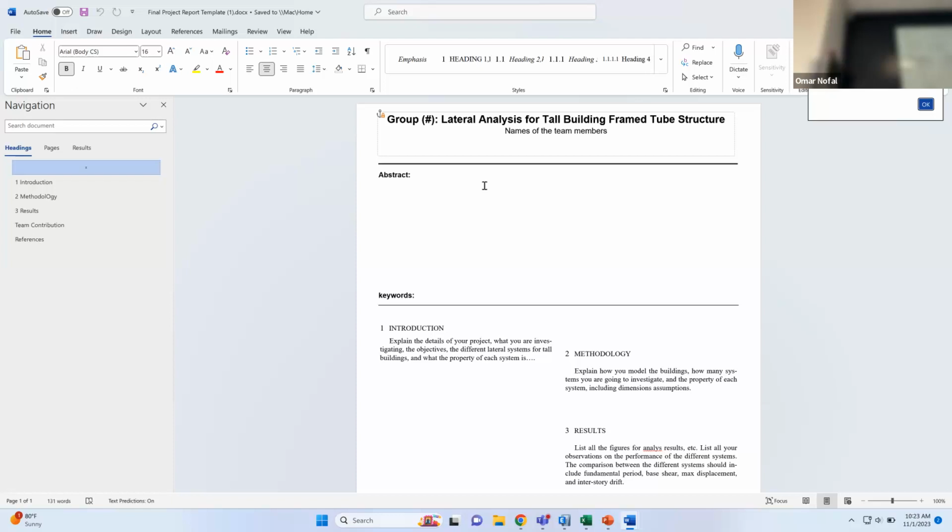the total displacement of my building is 2 meters, and I know that this is high enough. We can do this to decrease it. We can increase the shear wall thickness. We can add more shear walls. Tell me some recommendations on how you can decrease this displacement, okay? What we are doing is not a real project. We are just doing a practical exercise so that we can understand how the lateral performance of the building looks like. Let me show you a project from last year.